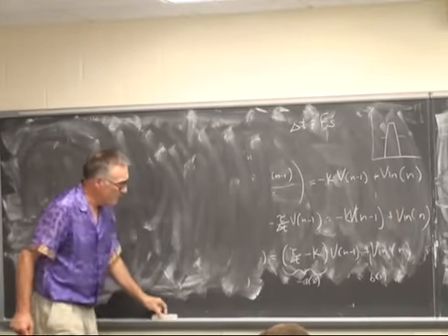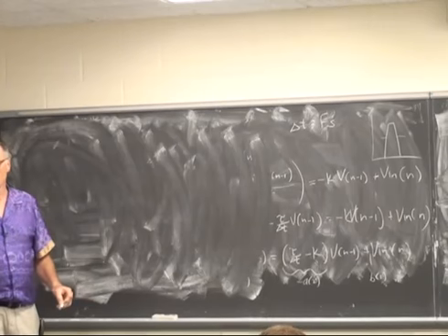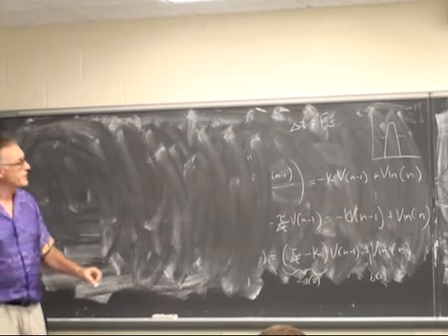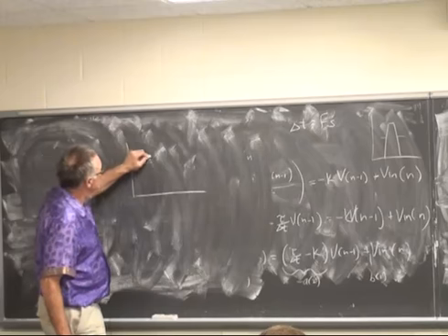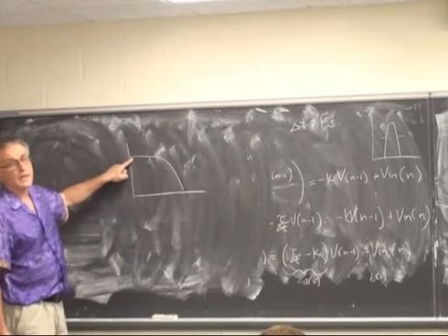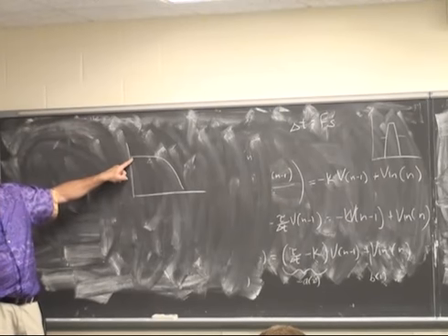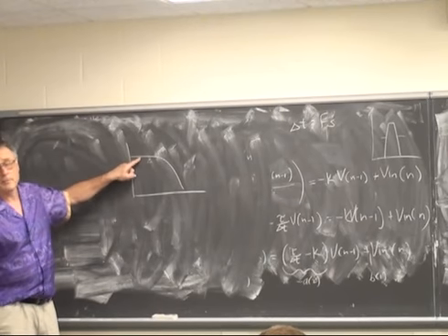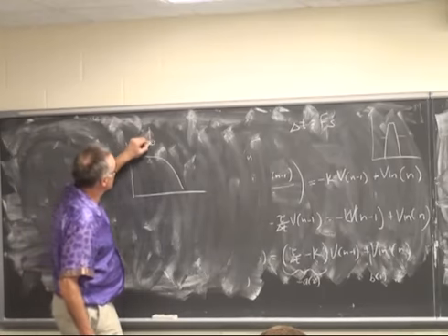is to use MATLAB. I'm going to ask you to build Butterworth filters. Butterworth are optimally flat in the sense that the slope of the amplitude function has all 0 derivatives at f equals 0. Okay, so it's optimally flat in that sense. I'm going to ask you to use a Butterworth filter.